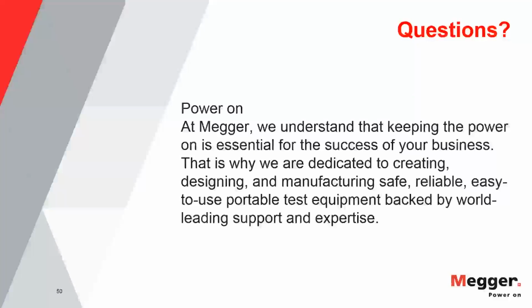This is Robert, and just to add to this, keep in mind that the main reason why the VLF technology was invented was because the DC hipot was not available anymore. So this is a tool to replace your standard commissioning test and maintenance test withstand. And the cosine rectangular naturally has a much higher test capacitance than a sinusoidal test set because of the physics involved. Now, the DAC is mainly a PD diagnostics waveform.